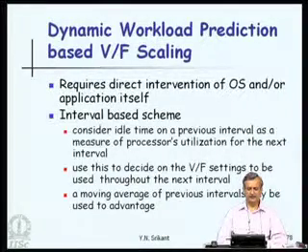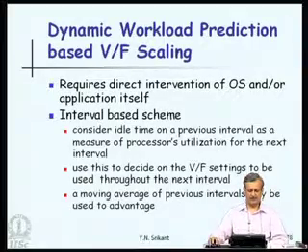This requires direct intervention of the operating system and or application itself. In interval based techniques, as I said, the idle time in a previous interval is considered a measure of the processor's utilization for the next interval. So, the assumption is whatever happened in this interval will happen in the next interval also. Use this to decide on the voltage frequency settings to be used throughout the next interval. It is also possible to use a moving average of the previous intervals, and this can possibly give some better advantage.